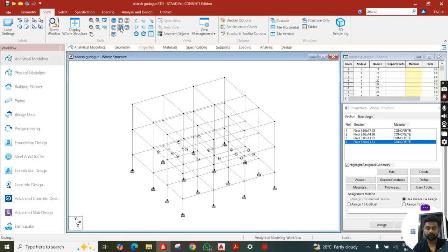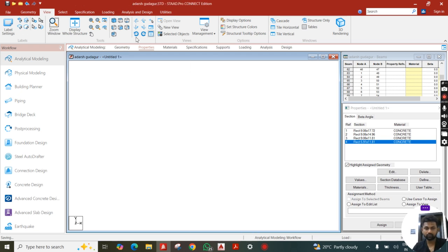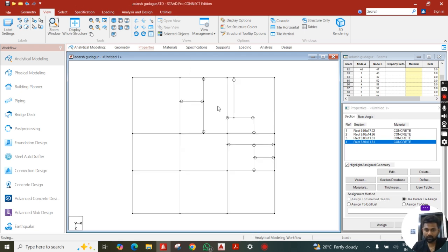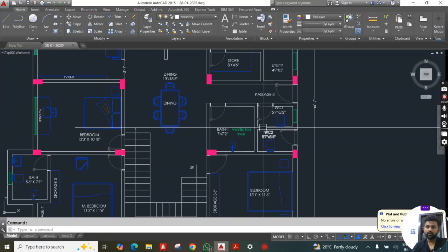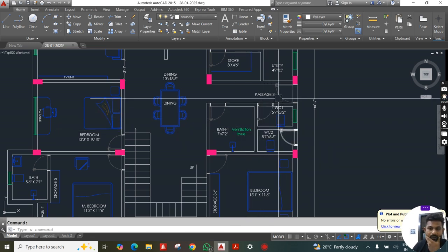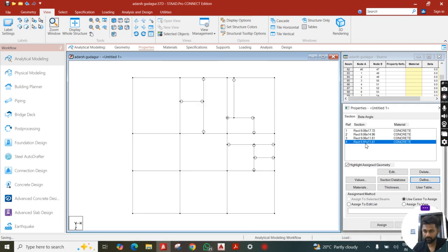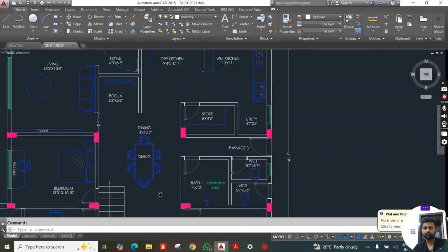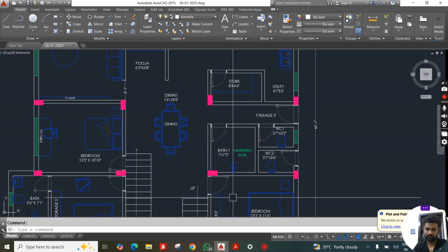So let's start with the plinth beam. So all the secondary beams, see, ground floor, this does not take a lot of weight, this doesn't take a lot of weight, right? So this one and this one, we can go with 6 inches, and this one, yeah, we'll go with that.